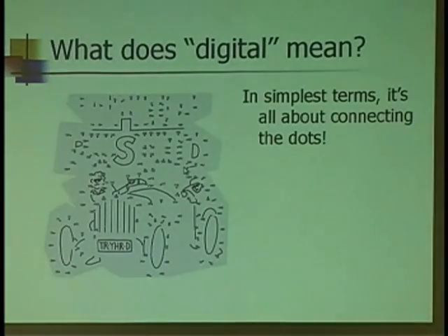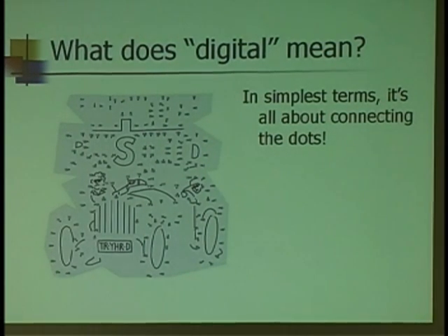But what is a digital source? It's an oscilloscope. When you start looking at sampling rates, what you're asking the scope to do is, it doesn't draw a real-time trace. It collects data just like a digital multimeter does, and it plots those points on the graph. It connects the dots. Now, the more dots you have, the more accurate the representation you have on your screen.